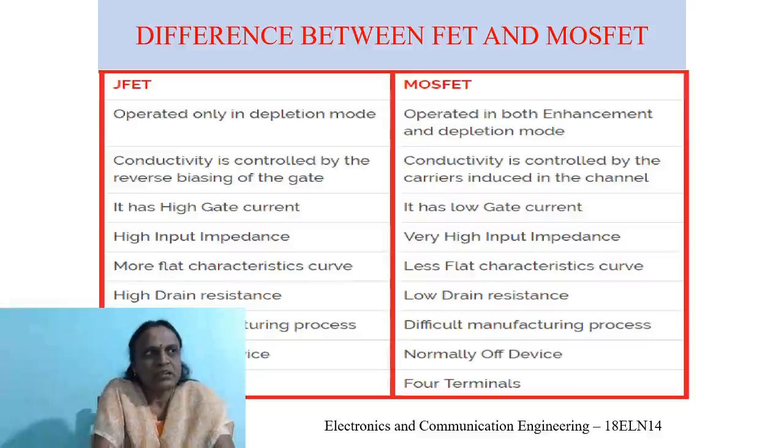Next, in FET, the relationship, that is the Shockley equation between VGS and ID, that is the input voltage and the output current, is used to define the transfer characteristics. Initially in session 4 we saw that, and it is a little more complicated, but not linear. Therefore, we can call FET a square law device.